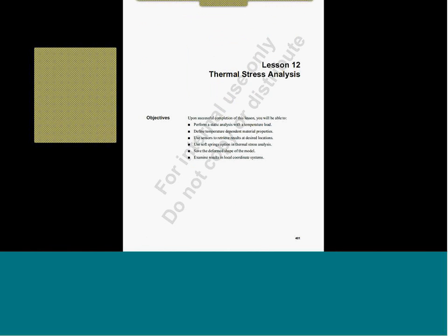Thermal analysis, an interesting concept, and I have to convey a bit of segregation here. Please try to understand. Yesterday morning, on the first day, we discussed this topic as more of a body load and not a stress load or a joint load. Please remember that. Also remember that in Simulation Standard, we can only analyze the stresses that are coming because of thermal load.